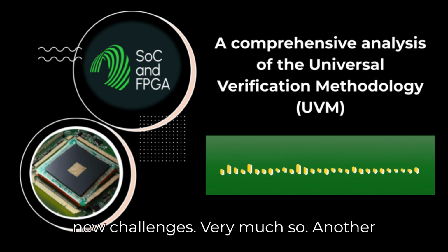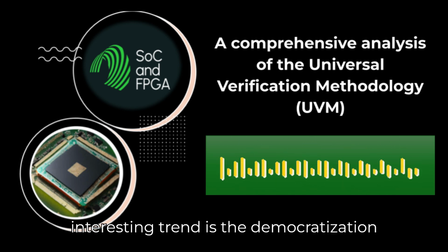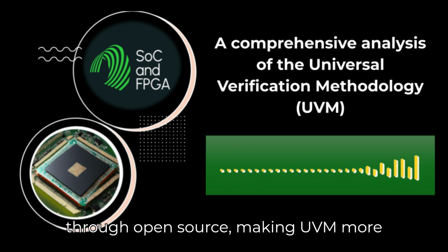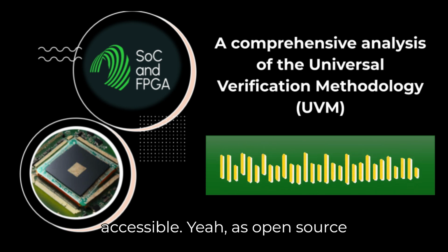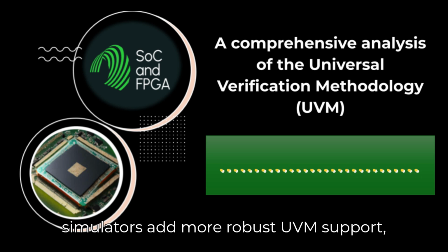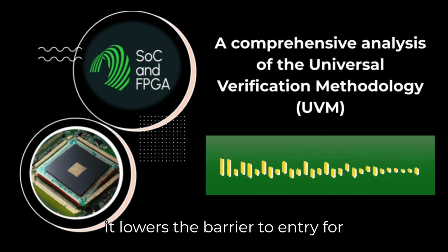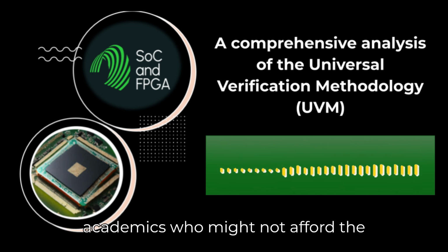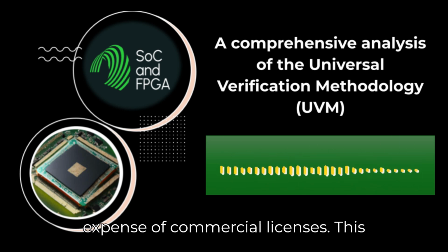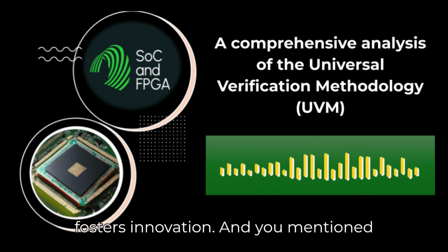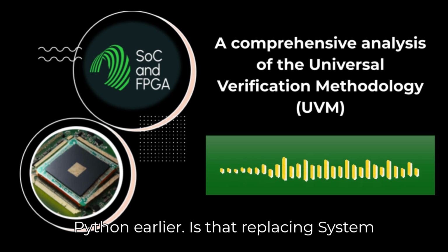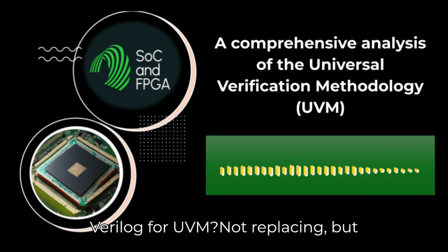Very much so. Another interesting trend is the democratization through open source. Making UVM more accessible. Yeah. As open source simulators add more robust UVM support, it lowers the barrier to entry for smaller companies, startups, and academics who might not afford the expensive commercial licenses. This fosters innovation. And you mentioned Python earlier. Is that replacing SystemVerilog for UVM?